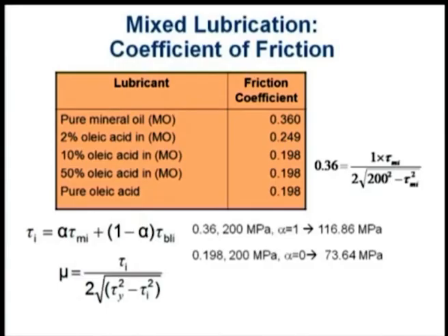When we talked about fluid film lubrication, we were talking about only pascal, not even reaching kilopascal. When we are talking about EHL and viscosity thickening effect, then there was a possibility of some kilopascal, say 1-2 kilopascal. But in absence of those lubrication mechanisms, when you are talking about boundary additives, just a monolayer or very thin lubricant layer on a surface, maybe some nanometers, the coefficient of friction is reasonably high, but the whole surface is covered with boundary additives.